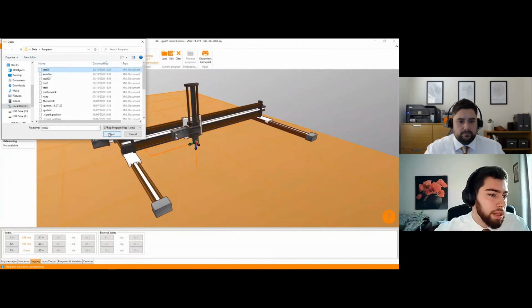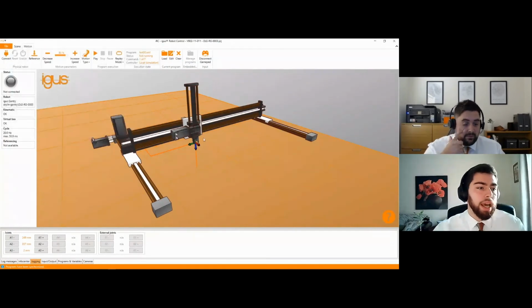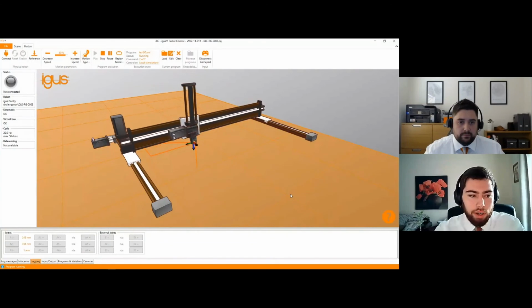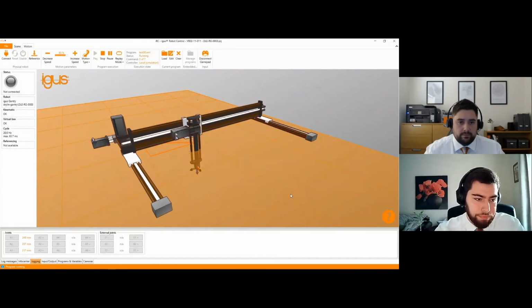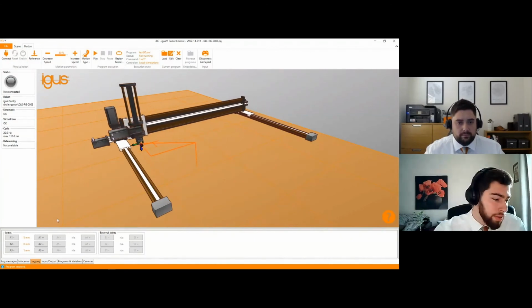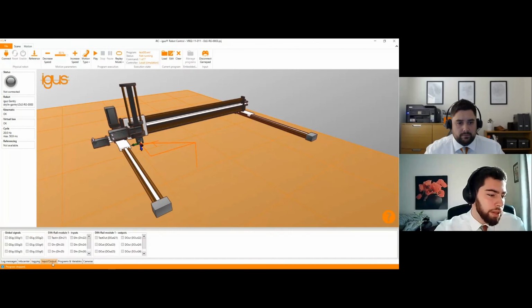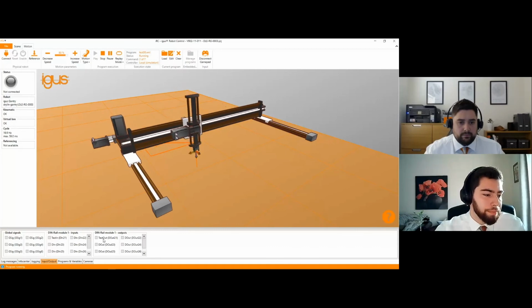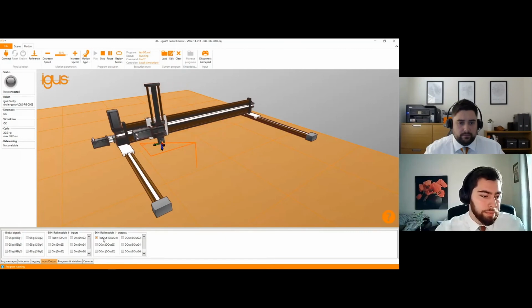So I'll select the program, press load, select the program, press open, and now the program is loaded. So if I press play, we're going to see the gantry performing the program that we have actually instructed. If we have a closer look on the bottom toolbar where we have the inputs and outputs, we can look at digital output 21, which should be acting as an on when we try to pick. There it is, and then disable when we are again at the start.